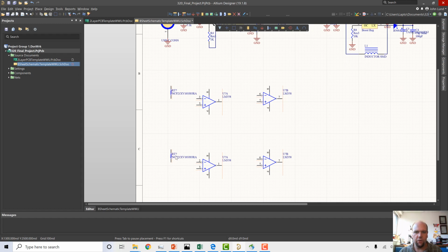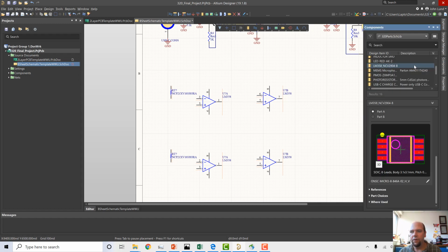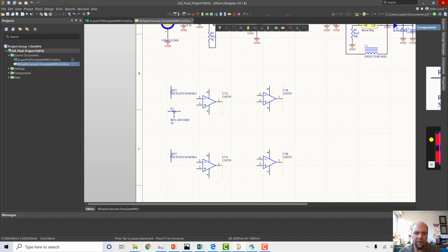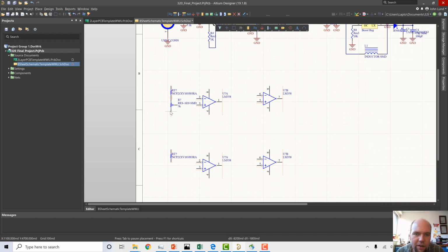So now I also wanted a pot in the middle here. So we can go to components. I think I had a surface mount. So, yeah, surface mount potentiometer here. So let's place that. Space bar to rotate. Put it, oh, look how perfectly that lined up there. Ooh, sometimes you get lucky. And then on the bottom side, we'll just put an 0603 resistor.